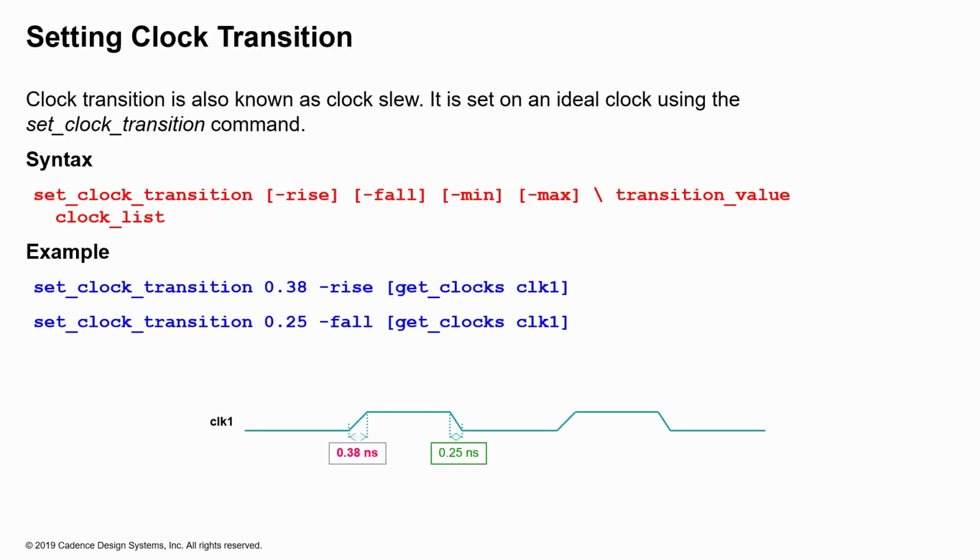Just like all other signals, clocks also have rise and fall times. The fan out of the clock is much greater than those of most other signals, so therefore the output slew degrades as the clock signal propagates through these cells. STA tools keep track of these maximum transition times on all the signals, including the clock.